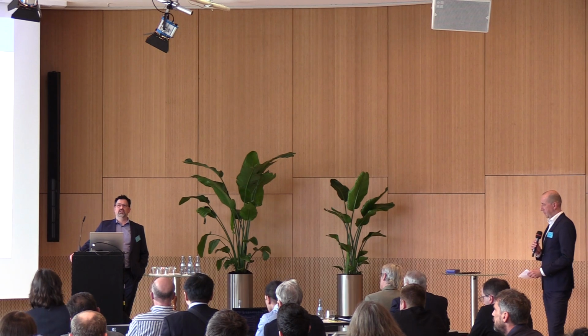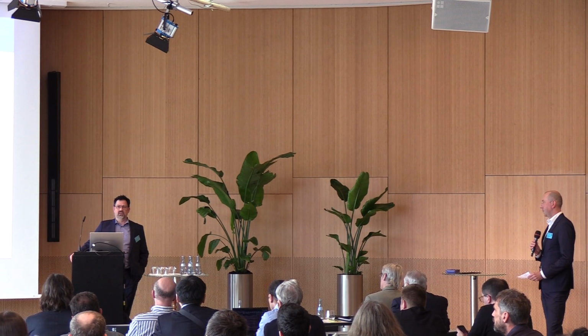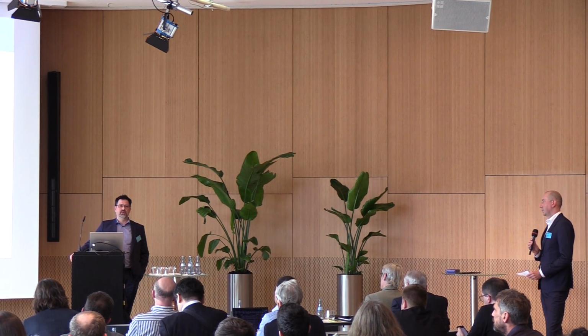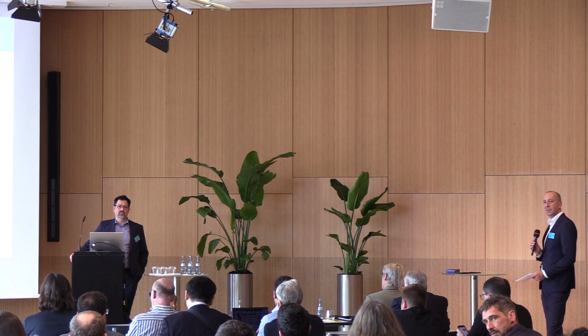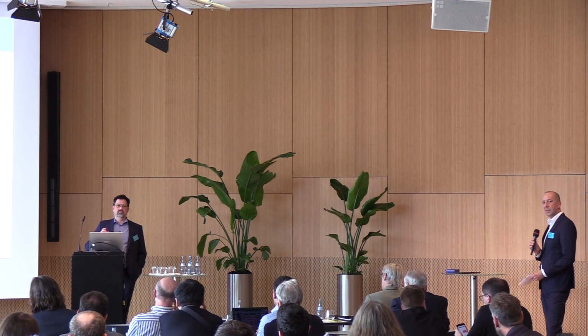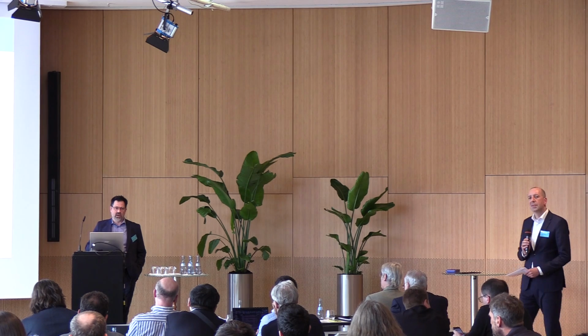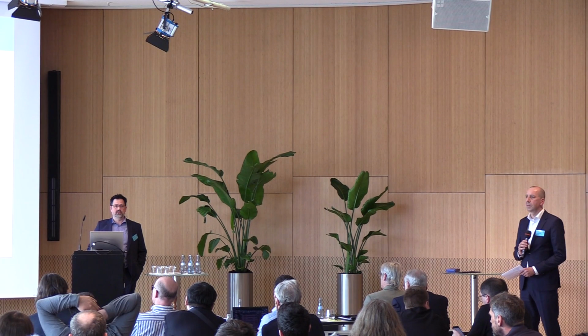As long as you can ensure that the stress data that you have computed is still in close agreement with the different material you're choosing, you do not have to redo the analysis. Okay. So the modulus change means, as soon as your modulus of elasticity changes, you have to redo your stresses. Otherwise, there's no need to do so. Okay.